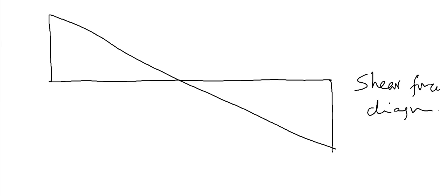Before coming back, now we'll go to our shear reinforcement design theory. Say this is our shear force diagram. So this is our Vmax. We do not design based on this. We calculate the shear force at d distance. At d distance we calculate the shear force Vu. That is our design shear force.